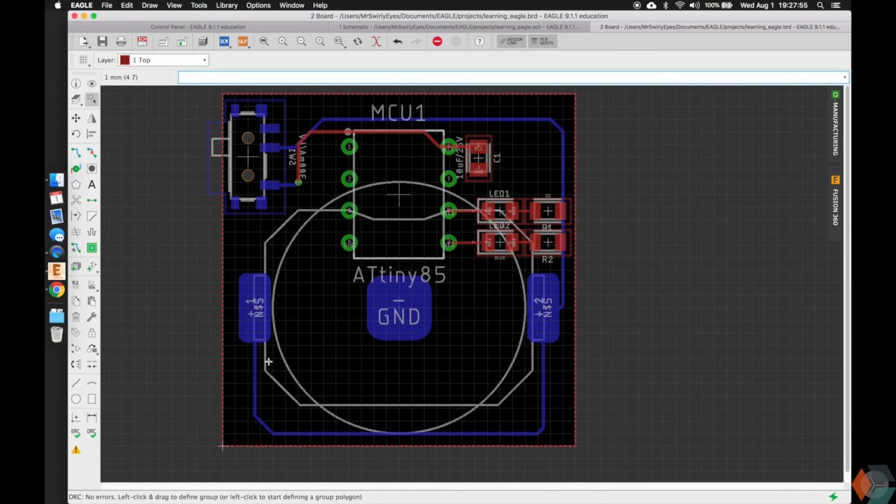If you made an error logically with your board, like this connection is not the right connection, but again, that's something that's meaningful to you, then the board won't work. However, for the capabilities of Arcatek to actually print this board, there are no violations. So just be careful. If you print this board and it doesn't work the way you want, doesn't turn on because you made a dumb or a silly connection, then that's on you. That's not on Arcatek. However, if you were to print this out and you got something that just didn't work, but you passed the DRC, then you may have to take that up with their customer support or so.